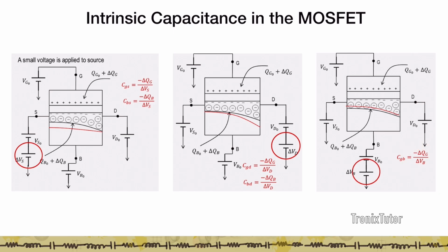Please note that we don't specifically call out a change in the gate voltage, because these have been individually modeled as CGS, CGD and CGB. By including these terms, you've already included what happens to the structure if the voltage on the gate wiggles. Part of it is shared with the source, part of it is shared with the drain, and part of it is shared with the substrate.